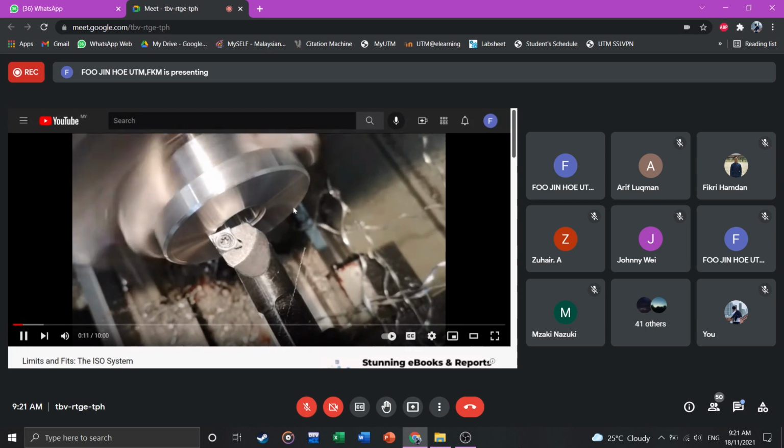This is the cutting tool that I mentioned about. You see that the sharp edge here is used to cut. So this is a single point cutting tool. There's another one called multi-point. The chances for the multi-point to fail are lesser, or you need a lot of wear and tear in the multi-point cutting operation to actually affect the size of, let's say, the hole.